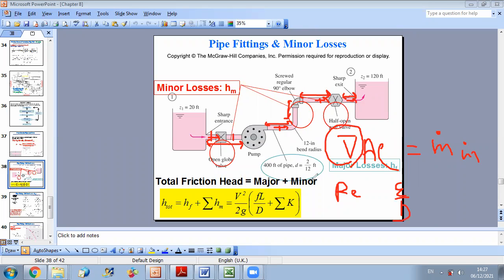So in case all pipes here, all pieces are characterized by the same roughness and same diameter, which will induce the same Reynolds from the continuity equation, I can use one friction factor for all of these parts, and just L will be the summation of all lengths, yani length of this part plus this one, etc.